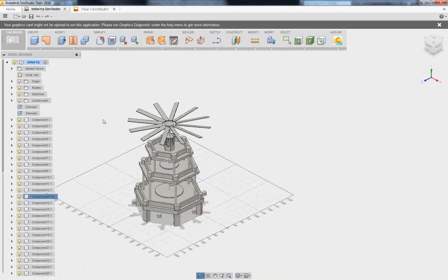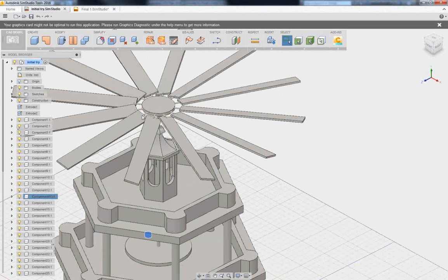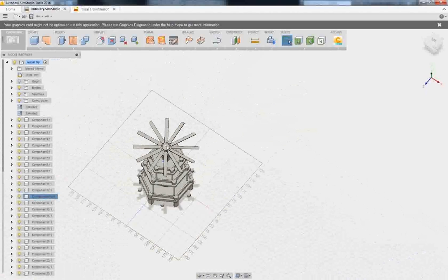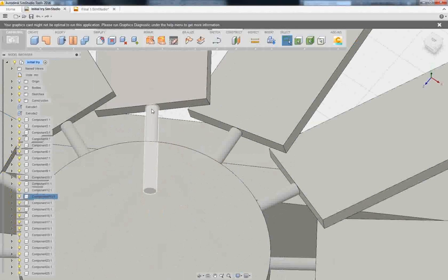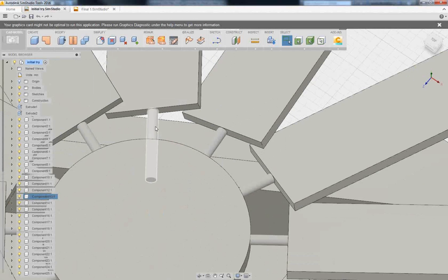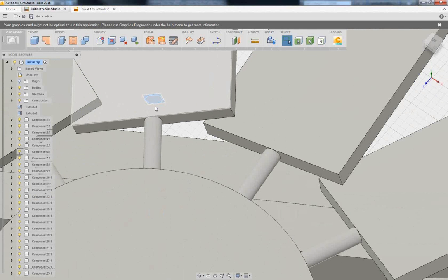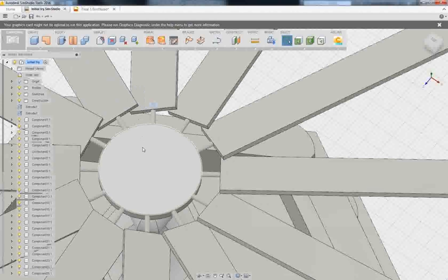And then my meshing failed on surface meshing for starters. So I was looking around and I saw these little tick marks on the blades. And I asked James, he didn't initially know what caused it, and I don't know if we ever completely figured it out, because it's really just a couple of fairly simple pieces of geometry, a rectangle and a cylinder that's going to be hitting it. But if you see what happens when I highlight here, there's these hidden surfaces. So it took me a little while to find them, but I had to remove those. That was probably my first nasty thing that I had run into.